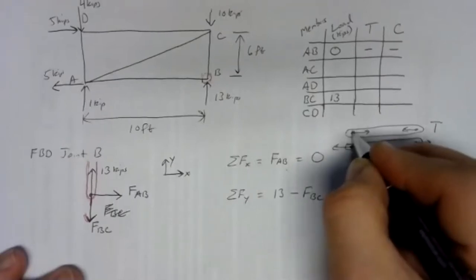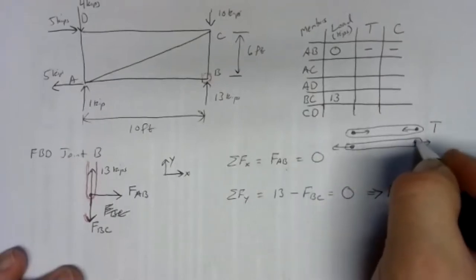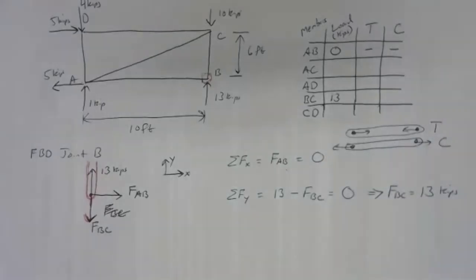So really emphasizing that it's the joints we're looking at here. That's compression. In these types of problems, in method of joints problems, compression is shown by pushing the joints apart. Only a member in compression can push its supporting joints apart because only something in compression can spring outward. Only a member in tension can draw the joints together because only a member in tension can shrink back to its original size.